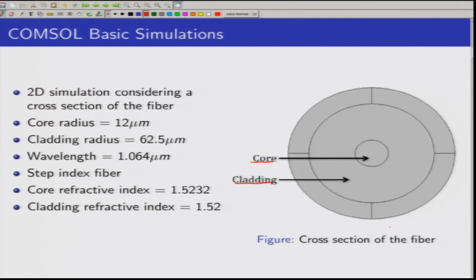Now, let us take a moment and, with the information given in this slide, calculate the V number. It would be appreciated if you pause the video for a couple of minutes, look at these parameters and calculate the V number, and then based on the value you get, comment whether this fiber is a single mode or a multi-mode fiber.